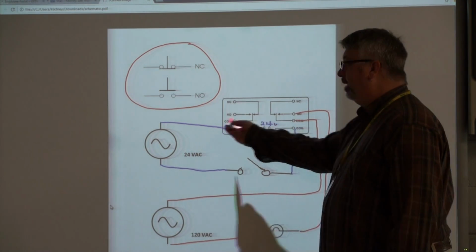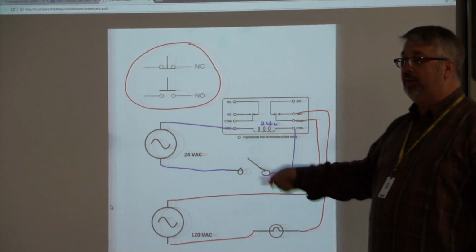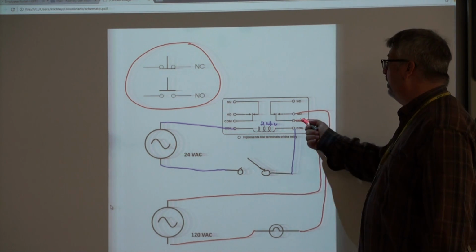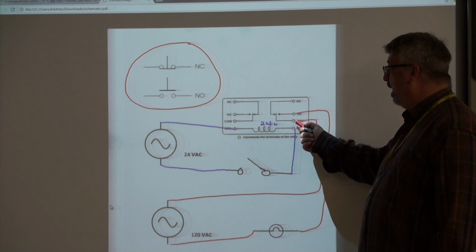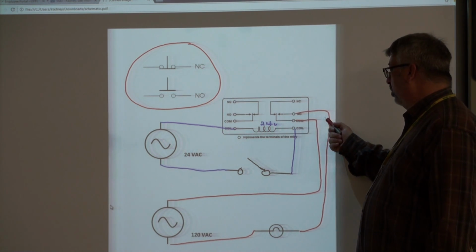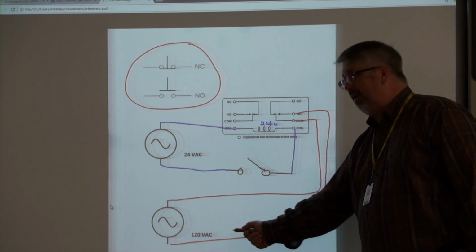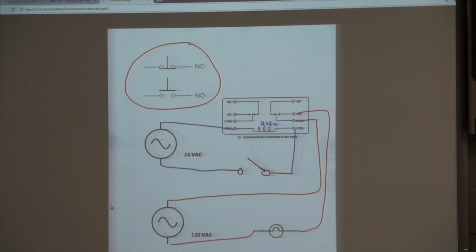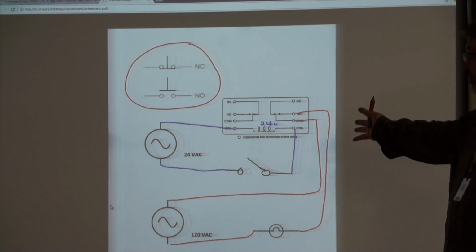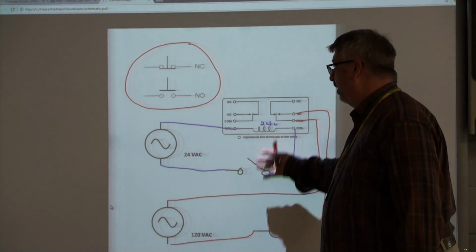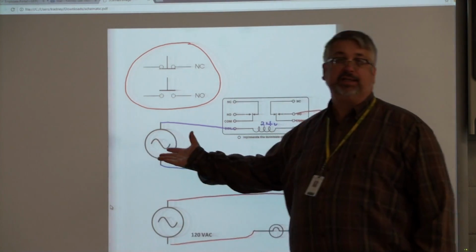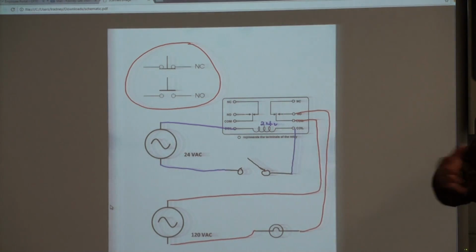So, independent circuit: switch operates coil, contacts change, and when the contacts change, the 120 volts that we're applying to this common go through the normally open to one side of our lamp, out of our lamp, back to our source. Electrically controlled switch, completely independent, two different source voltages: got a 120 volt source for our lamp, 24 volt AC for here, but this could be a 9 volt DC source that we're switching. Again, they're totally independent of one another.